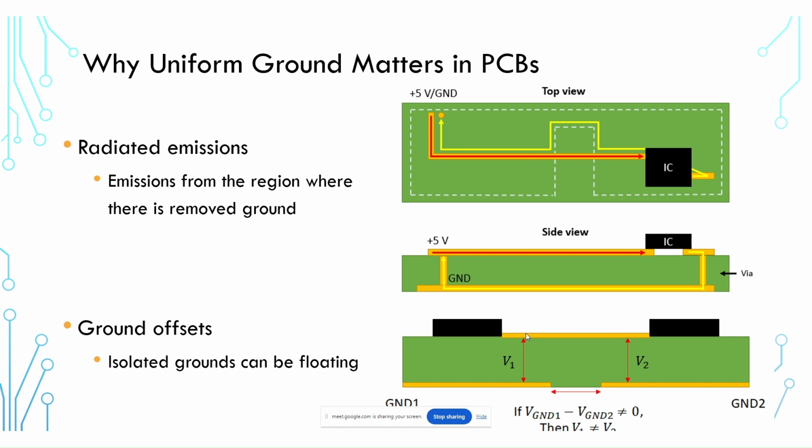So rather than taking the voltage difference between a trace and two different planes, what a differential interface does is you would have two traces here, and you're just measuring the voltage between the traces. So differential interfaces are actually quite important in mixed signal PCBs, where you have a sensor, and the sensor has a differential output.